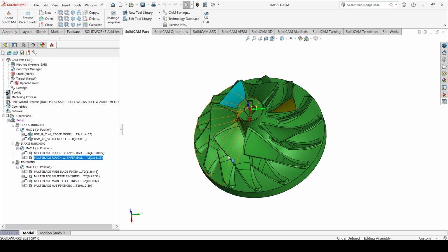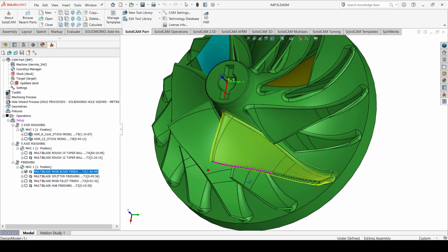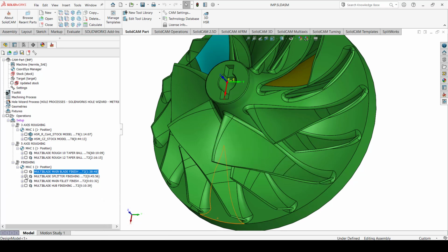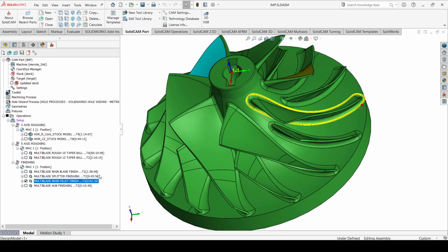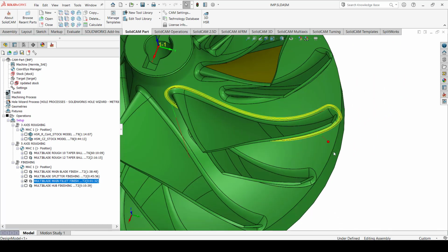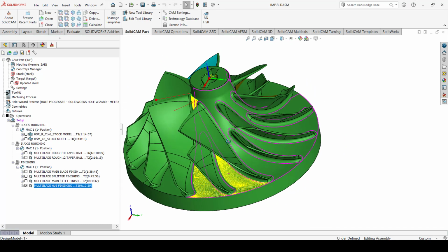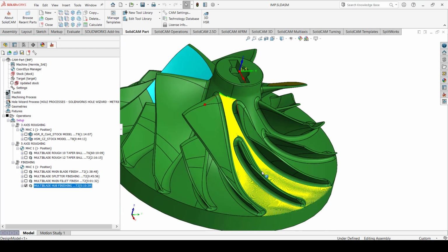Multiblade machining also constitutes toolpaths for finishing. So you can use only the blade area and generate the toolpath for finishing. You can also generate the toolpath for splitter finishing. You could also generate the toolpath for the bottom fillet only. So you can pick up the fillets and you can finish the fillets for this blade. And also it has options to do machining for the floor.